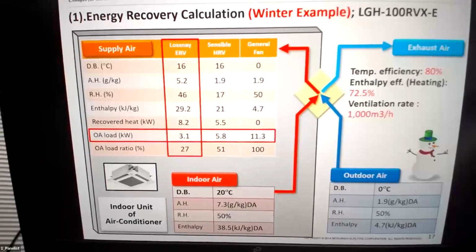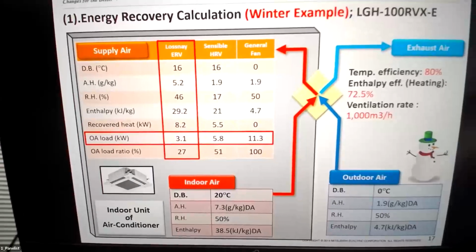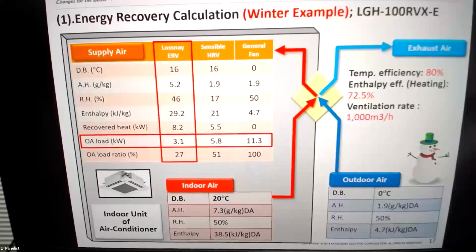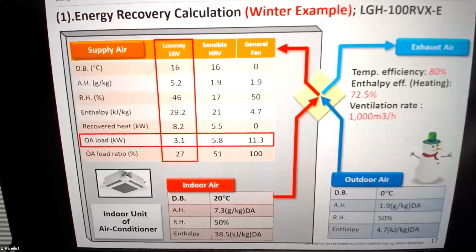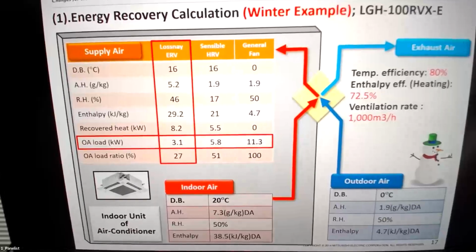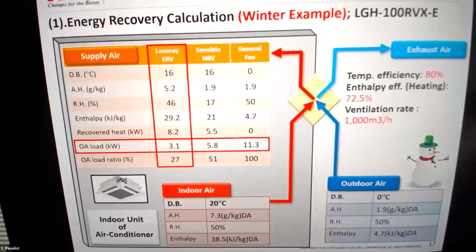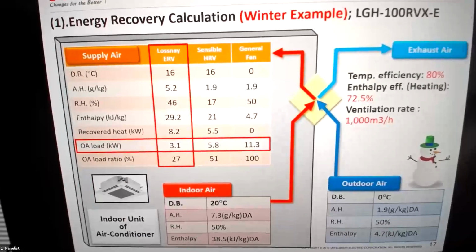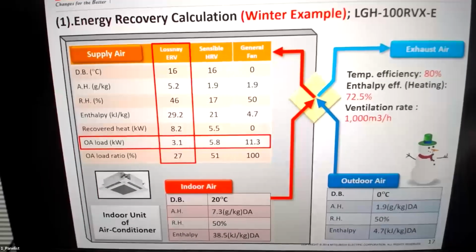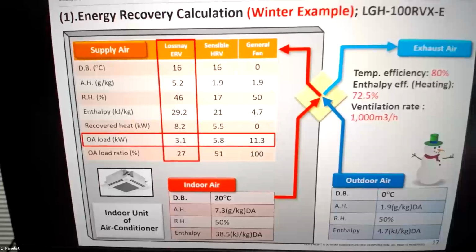Less energy, I mean cost. However, sorry, here, sensible heat exchanger without moisture recovery, but temperature, yes. In that case, for example, temperature recovery efficiency 70%, 0% of humid recovery. So temperature 16%, good, but absolute humidity is the same as outdoor, dry. So we need to add humidity by something, a humidifier or something, it's cost.